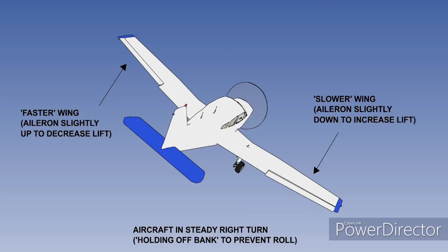The deflection, although probably undetectable from control column position, is greater for low speeds than for high speeds. The inner or lower wing will have a slightly greater angle of attack than the outer wing because of the difference in aileron position, and may reach the critical angle first.